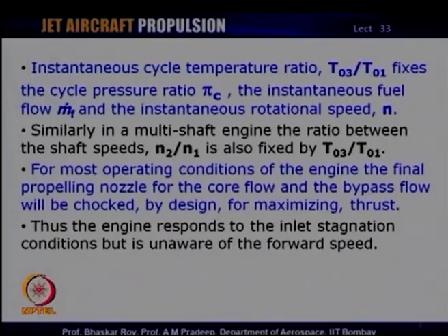If we have a multi-spool or multi-shaft engine, the ratio between the shaft speeds n 2 by n 1 also is getting fixed by the temperature ratio T03 by T01. So, that is another issue. If you have a multi-spool engine, different spools run at different speeds, and then they come into the picture again, and they would also need instantaneous change to conform to the changes of the four fundamental parameters that we have talked about.